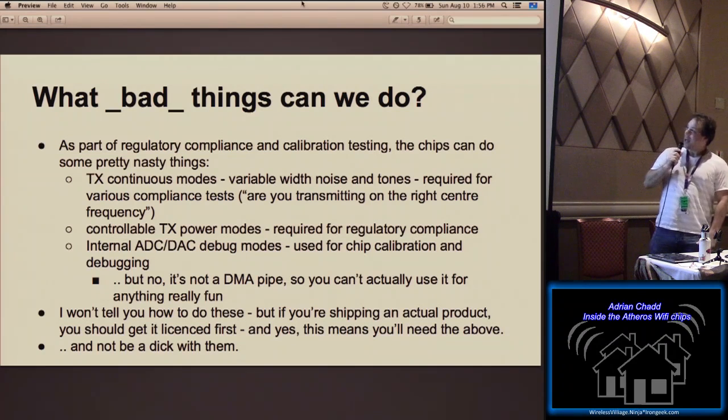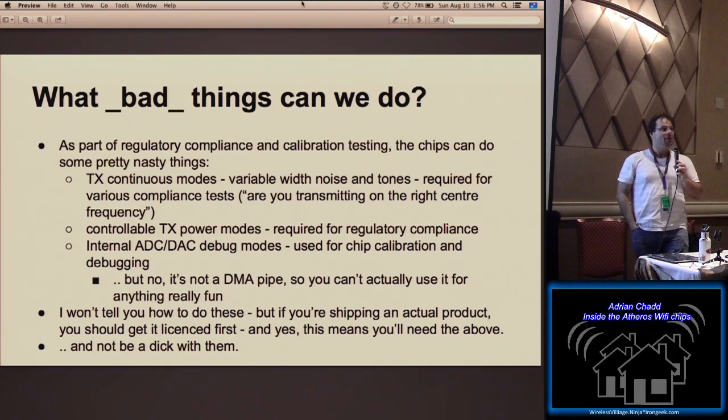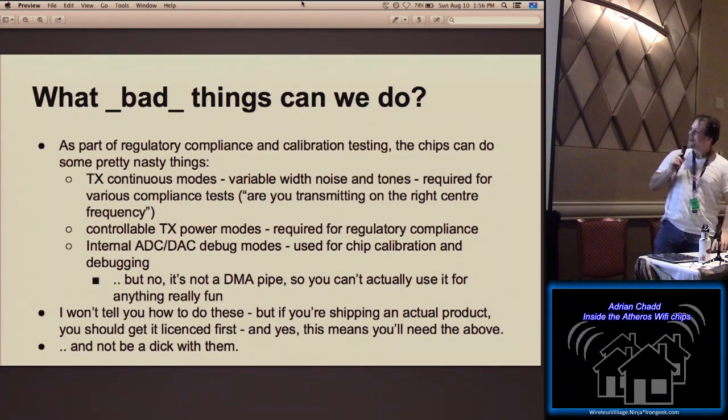So one of the things that happens is you need to be able to verify that your chip is transmitting on a particular center frequency and not drifting over time. Otherwise, it's not going to interoperate well with other devices. So you can put the chip into a mode where it just blurts out a tone. Now, if you did this in the real world, the Wi-Fi in your area shuts down. It's actually kind of pretty to watch. The minute you transmit a carrier tone at maximum power, you don't care about distortion, no one else's Wi-Fi works. Don't do it. I'm just telling you, don't do it. What you do is your own problem, but don't do it.